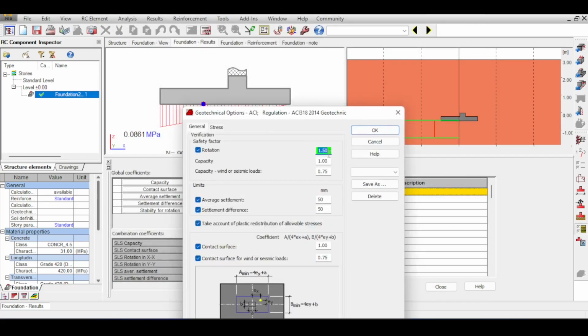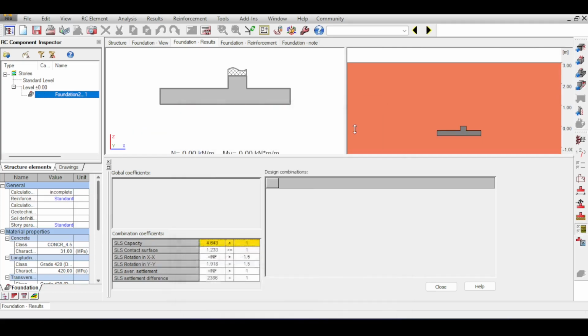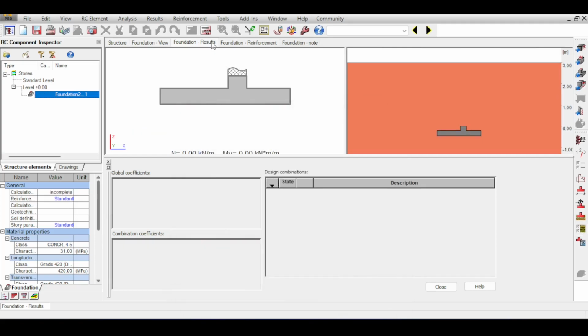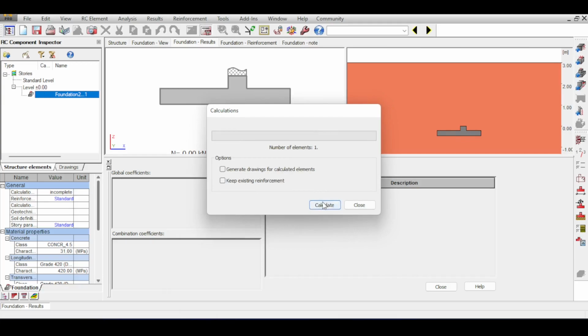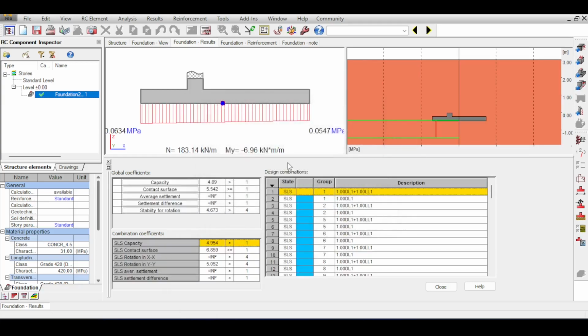However, if you increase the factor of safety to 5 or 4, for example, of course, this is an arbitrary value. You are responsible for it yourself. You need to check your design code. But if you change the factor of safety, then Autodesk Robot shifts the position of the wall. So this is the first thing I wanted to address in the design of retaining walls according to Autodesk Robot. Also notice that Robot tries to give you a semi-equal pressure distribution below the foundation, and that's the reason why it shifts the wall position.